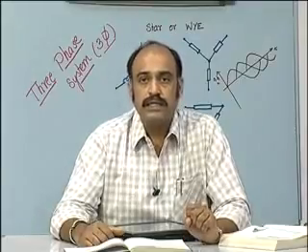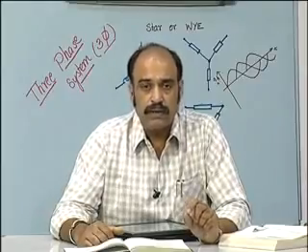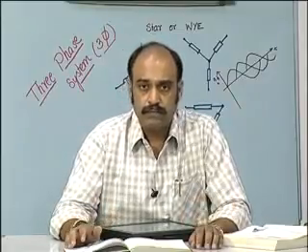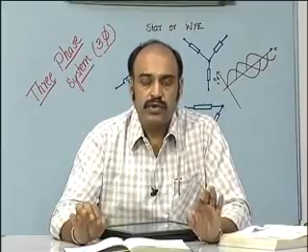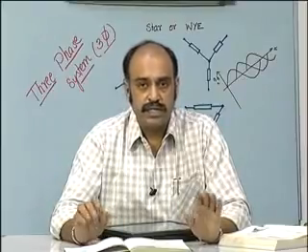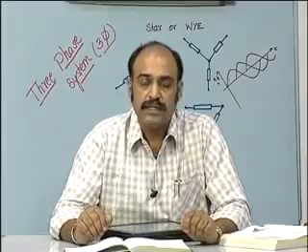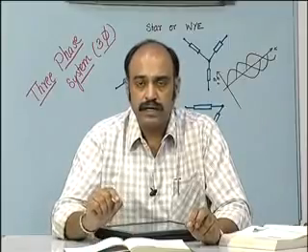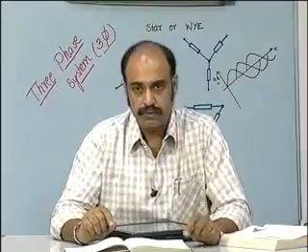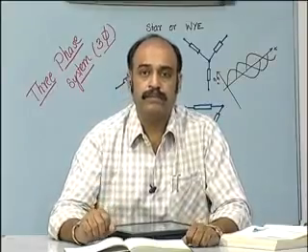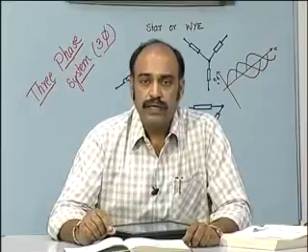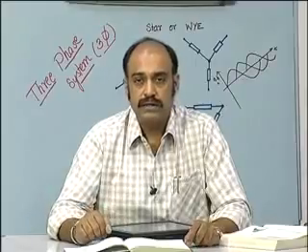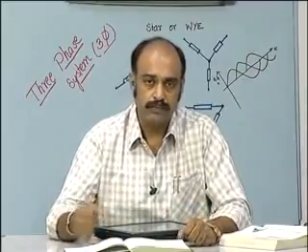The neutral points in the star circuits play an important role in the sense that if the loads are balanced, the neutral points can be left floating, because under balanced load condition IA plus IB plus IC is equal to 0, which we saw and discussed in the previous classes. Therefore, there is no need to connect the neutral point of the load to the neutral point of the source. There need not be a return path wire. As a consequence, we save in copper, since you just need 3 wires to connect a 3-phase source to a 3-phase load.